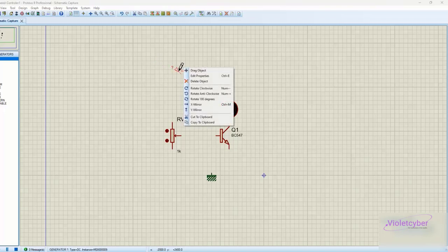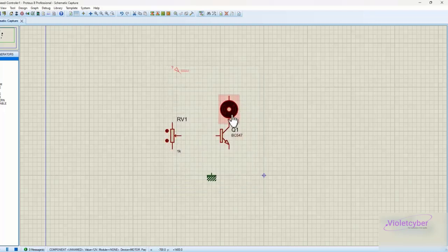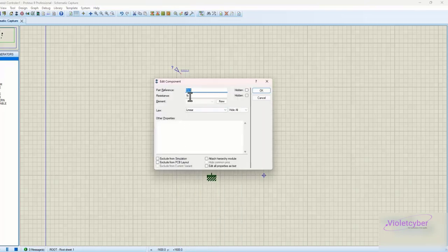First of all, for example, I set the voltage to 20 volts. In the simulation, we can give the motor a voltage of 14 volts, but it doesn't matter here; in reality, we have to pay attention to its working voltage. So our voltage is 20 volts. For the potentiometer, for example, I will choose 2 kilohms, because a higher resistance makes it easier to control the speed.